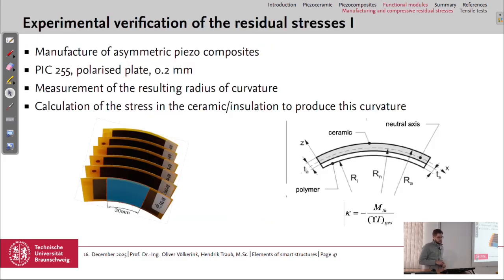These residual stresses can also be tested experimentally. A simple test is to manufacture asymmetric piezocomposites. So we have the ceramic at one side and the polymer at the other side, and with different residual stresses in the different layers, we get curvature after cooling it down.